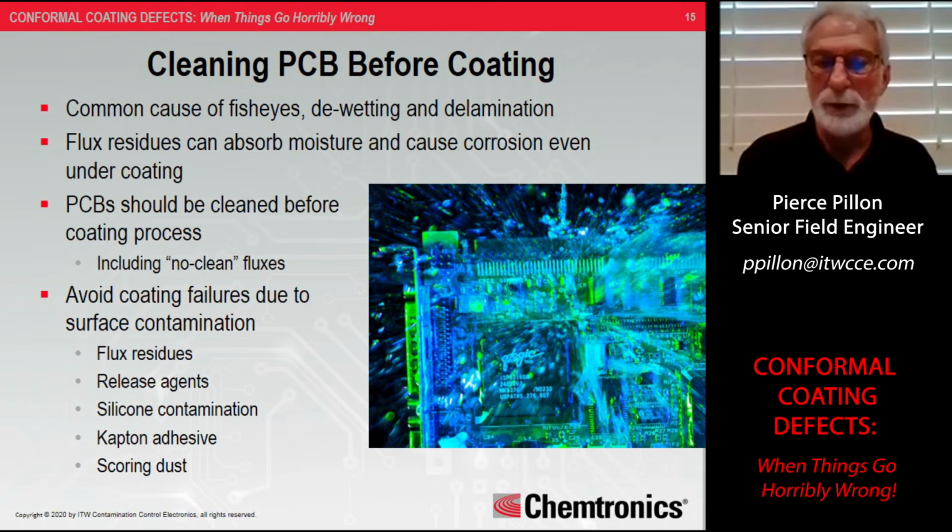There have been some instances where these are routed back to the use of no clean fluxes. It is not every no clean flux. It is not every coating. It's just certain combinations. People coat over no clean every day. But that potential exists of having a coating and a no clean flux residue that are incompatible with each other. So we always recommend cleaning before you coat.